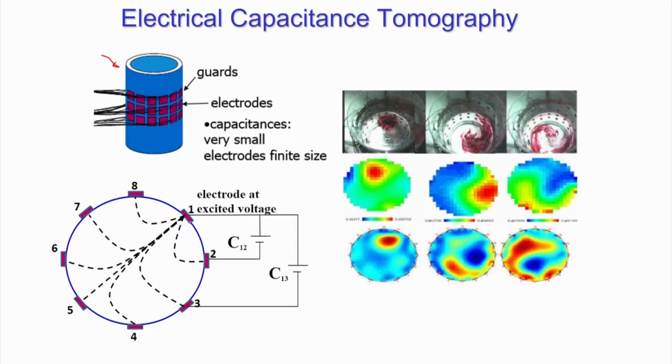The capacitance between these two, say 1 and 2, will change. You record how the capacitance changes in terms of the voltage change, and how the capacitance will change depends on what phases are present in between. This path cannot be linear, it is not needed that it will be linear, it will not need to travel like this, it can be any path. I have shown a tentative path here. Actually this is the mean path, it goes something like this. So, it will depend on how much of this path there is, and what phase is present in it.